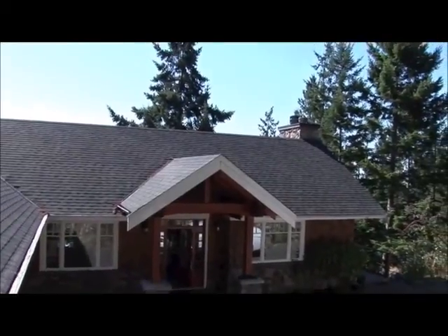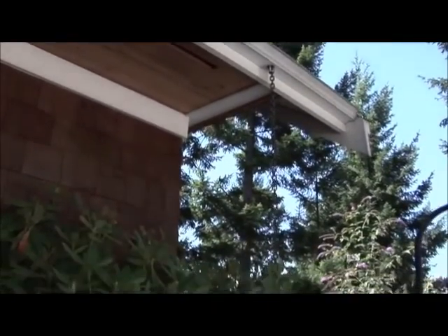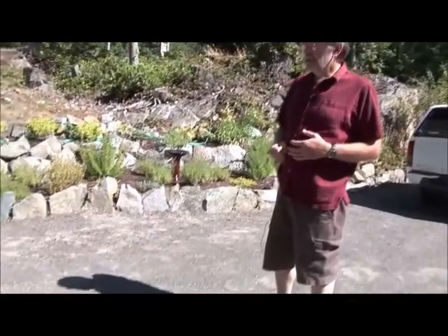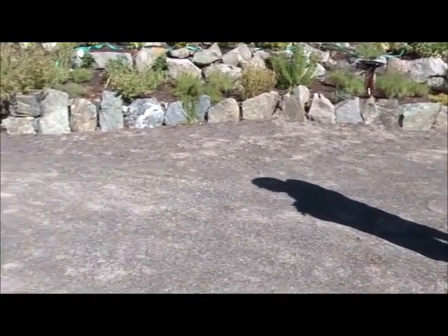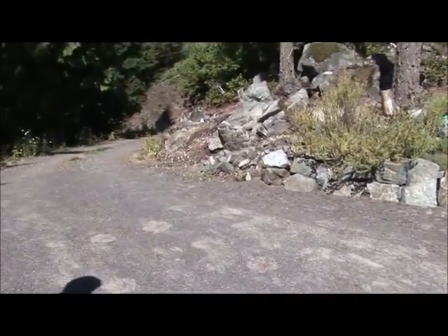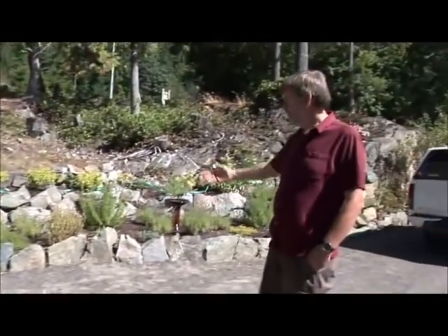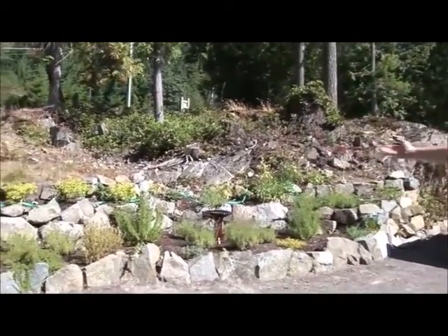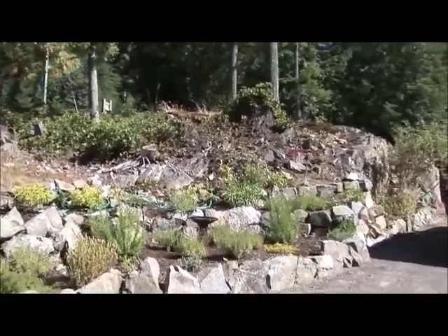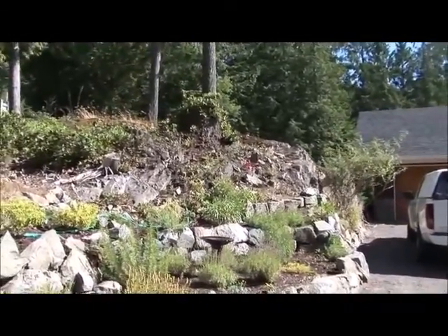The house contains other stormwater features. Gutter chains direct some of the roof water into the garden. If you look at the driveway, you'll see that it's granular, because that's another part of the restrictive covenant, no paved driveways, so that whatever falls on it percolates down. And in terms of the garden itself, it's a very limited garden area, but we just use a combination of the soaker hose and hand watering.